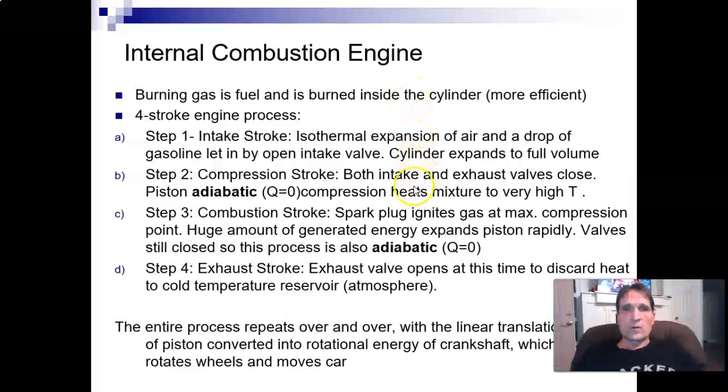Then the second stroke, the compression stroke, where the intake and the exhaust valves close and the compression happens so rapidly that heat cannot be added or removed. We can model that stroke as an adiabatic compression. Then the spark plug ignites and generates a huge amount of heat, which expands the piston. Again, this happens so rapidly that we can assume that negligible heat enters or leaves, so we can approximate that combustion stroke as adiabatic.